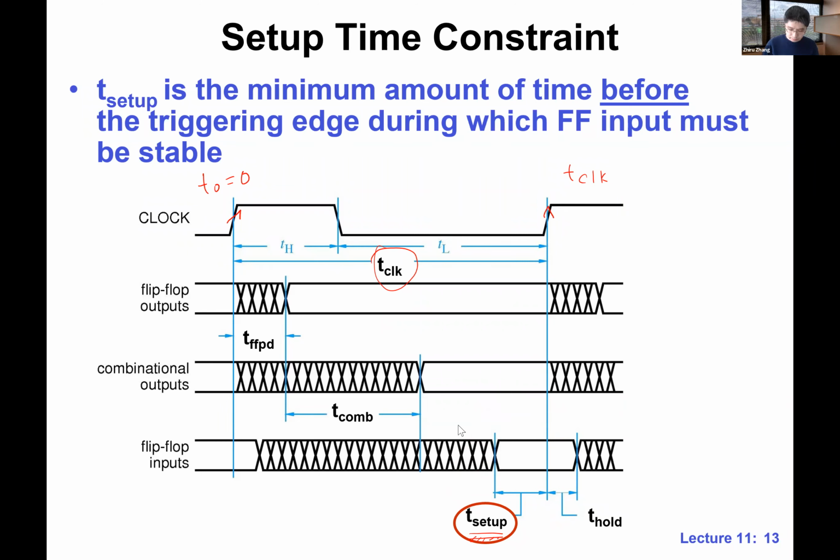But when exactly is this deadline? Let's just extend this line. What is this time? Can you guys tell me? Based on our reference time. Very good. T clock minus T setup. So far so good. So this is our deadline.